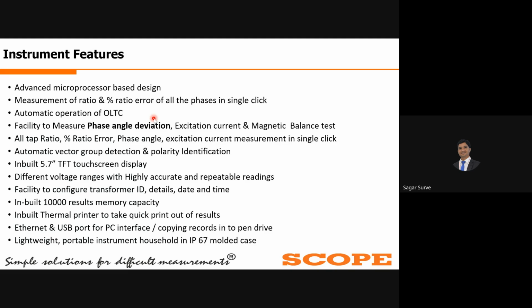Whenever we are conducting the test for transformers which have a maximum number of taps, like 21 taps or 17 taps, at that time it is not easy to operate the transformer for each and every tap test. So for that, if you make the setting for the transformer in this instrument, then the instrument itself will conduct the test, and the facility to configure the transformer ID details is possible.